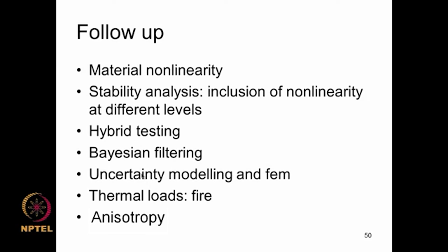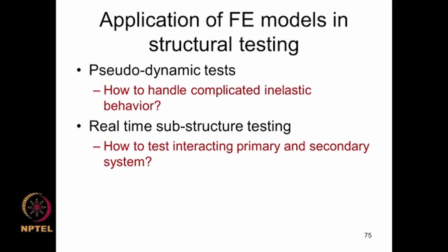I would like to spend a few minutes explaining what is hybrid testing and what are the issues about uncertainty modeling and the finite element method. Now, what is the role that finite element models play in structural testing? There are different testing strategies available in vibration engineering. One is what is known as pseudodynamic test, that typically helps us to handle questions about complicated inelastic behavior under dynamic loads using basically static methods of experimental investigation.